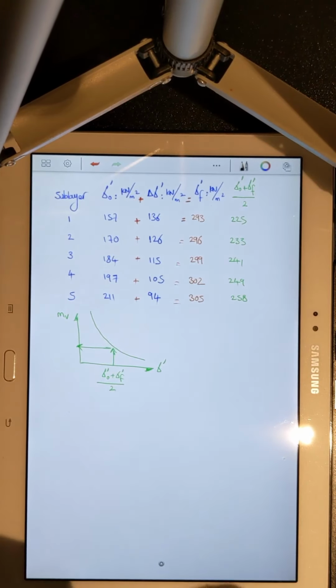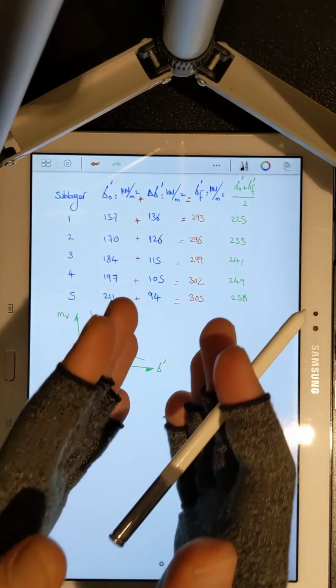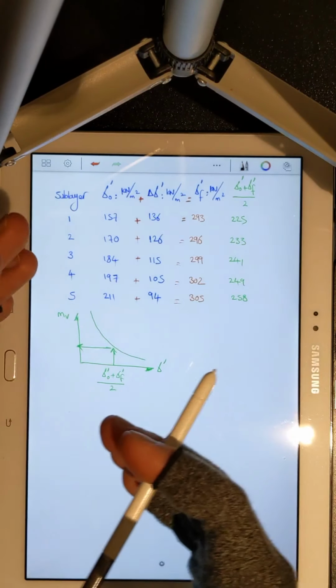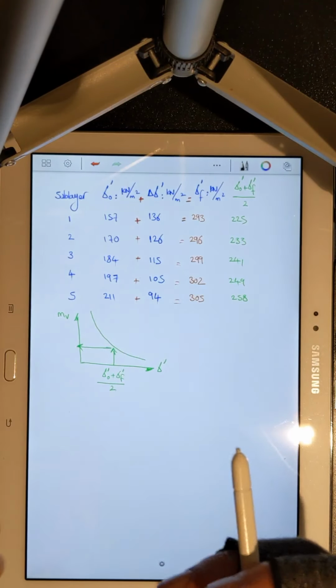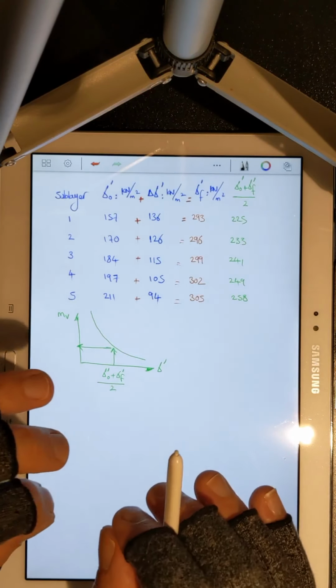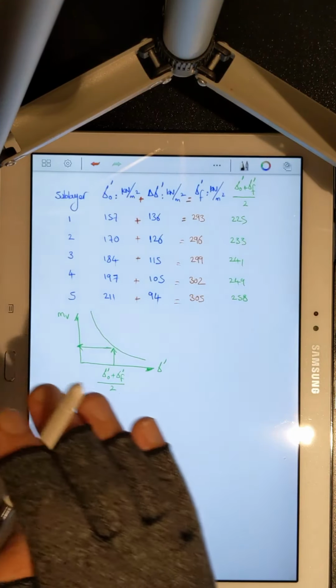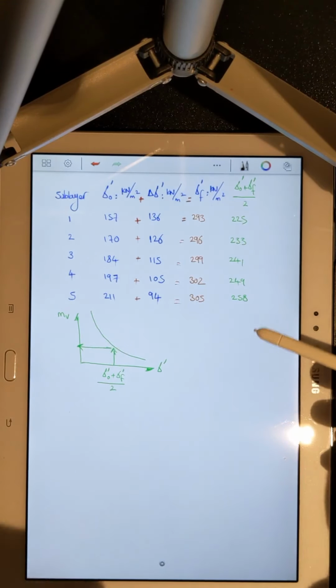Or again, you can be conservative. If these values are falling in a bracket in your table of M sub v versus sigma dash, you can go for the larger number of M sub v. It's up to you. But since through all this exercise, I'm being precise, I'm trying to be accurate, I have done linear interpolation and I will report the true numbers here.